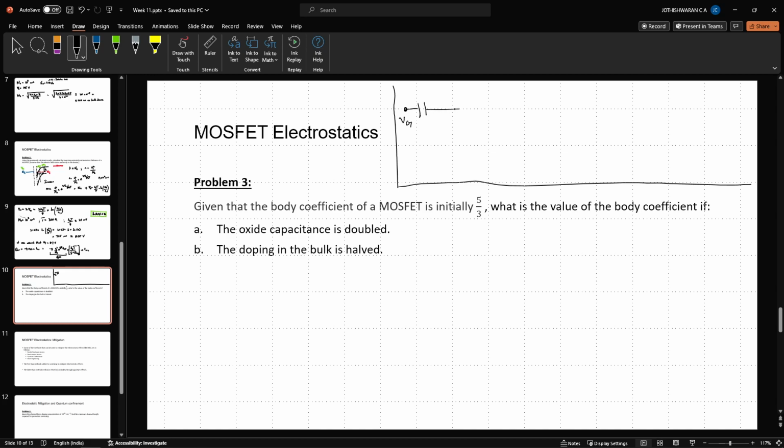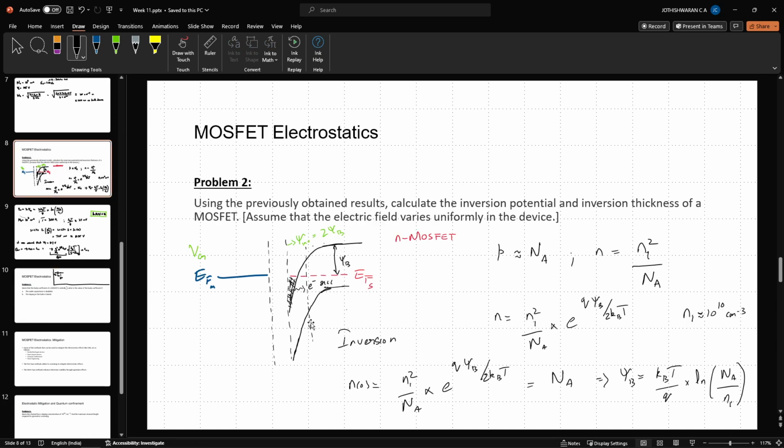modeled as follows. So I know that there is an oxide, which of course acts as a capacitor. So this is a dielectric. I have a metallic electrode on the one side, and when inversion is achieved, I can assume that the other side of it also has metal-like behavior, because it is electron rich. So that brings me to the interface point. So this corresponds to the y equal to 0 point. So I have the oxide capacitance over here. And what we should remember is, even past the complete inversion region, there is a depletion region here.